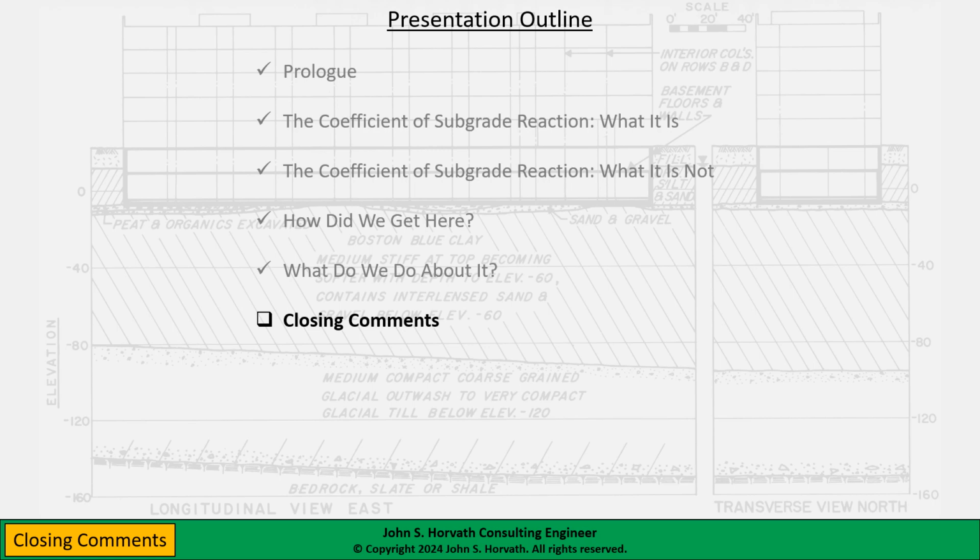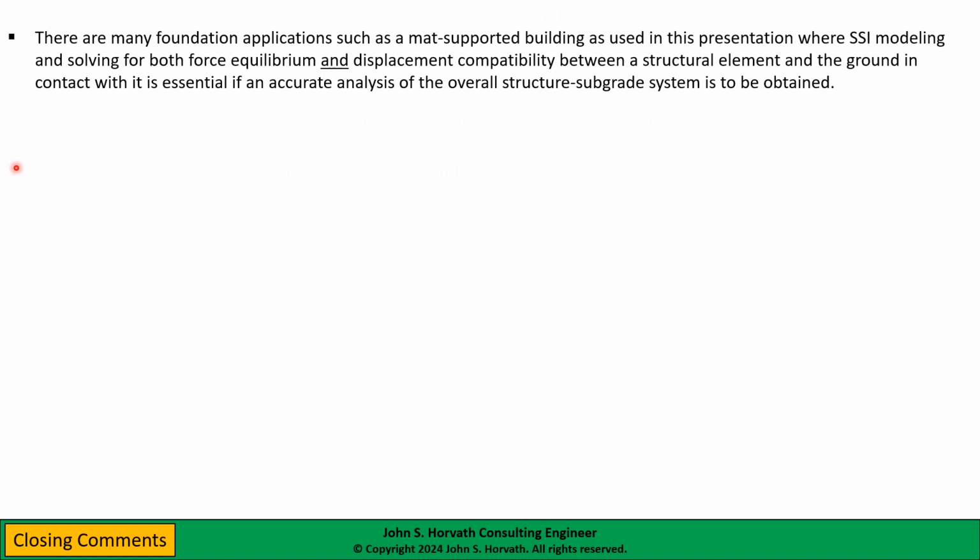So to wrap things up with some closing comments, there are many foundation applications, such as a mat-supported building, as I've used in this presentation, where soil structure interaction modeling is a must. That is, we have to consider both force equilibrium and displacement compatibility between a structural element and the ground in contact with it, if accurate analysis of the overall structure-subgrade system is to be obtained.